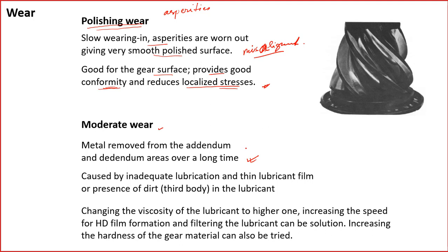And as I said, it is because of the sliding that is going on between the teeth, caused by inadequate lubrication. So lubrication is not good. That means sliding will be more damaging. There will be high surface stress. So we need to have good lubrication, and a thin lubricant film or presence of dirt can cause problems.